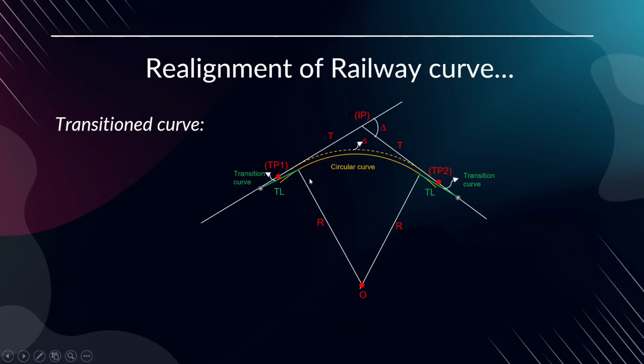So that is why every engineer has to periodically inspect the curvature, whether the alignment is proper or not. For that purpose, in Indian Railways we have the Indian Railway Permanent Way Manual. There are a lot of stipulations available, and it provides a schedule for the inspecting official periodically: how many months it is to be inspected, what all the parameters have to be recorded, and based on the existing parameters, they will come to the conclusion whether the alignment is correct or not.